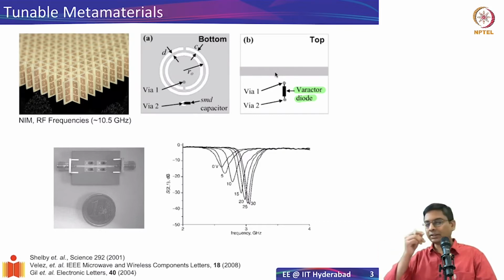that was designed. So in this case, you have split ring resonators, and it's meant to act like a notch filter. Okay, so it filters certain frequencies. So what happens in this case is that you have this side, these are known as SMA connectors, and then you can connect an RF signal into that, and then you can transmit across this device, and then you will get the output on the other side using a vector network analyzer.